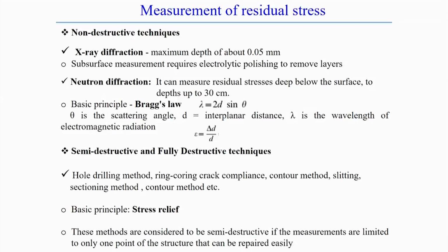It follows Bragg's principle, that lambda equals 2 d sin theta. Here, theta is the scattering angle, d is the interplanar spacing, and lambda is the wavelength of the electromagnetic radiation. Therefore, the strain is measured by the change in d. So, delta d by d measures the change. So, X-ray diffraction is a method to measure the residual stress.